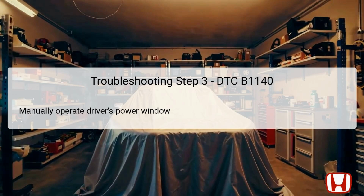In Step 3, you are required to manually open and close the driver's power window utilizing the driver's switch. This action is essential for checking if the window operates correctly beyond the digital diagnostics. Manually controlling the window can help diagnose mechanical issues that could complicate electronic problems.